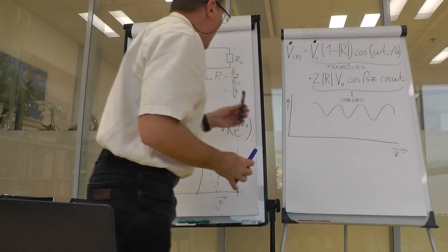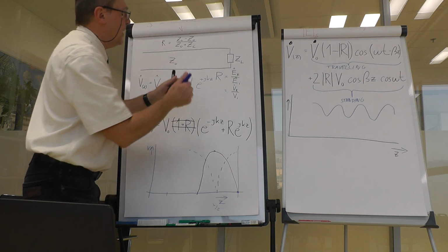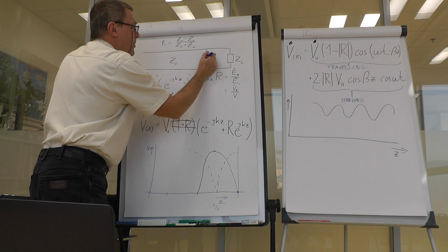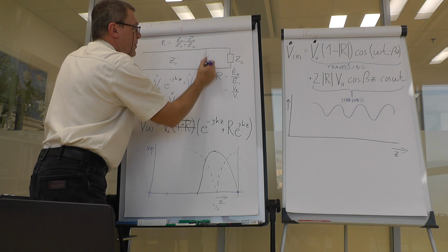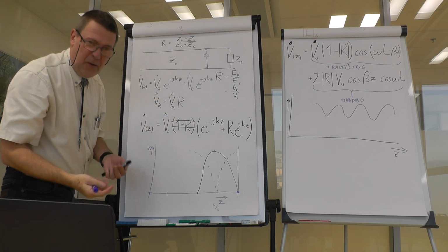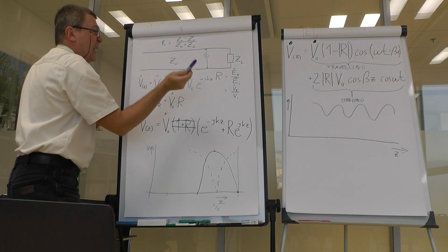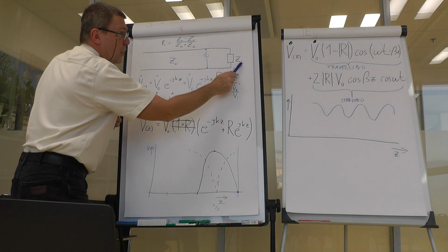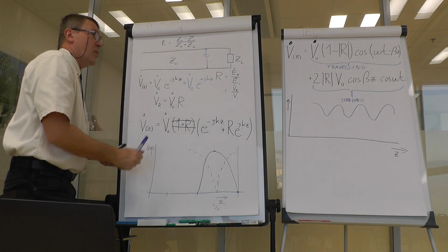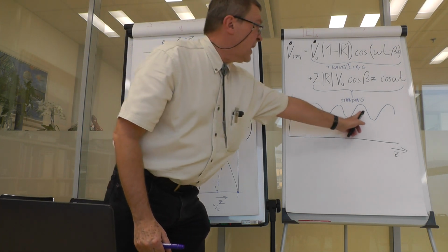If we would have, for example, a probe, a voltmeter, connected just on the line, or a voltmeter with a rectifier, and we would move it on the line in the case where Z0 would not be Z load, but Z load would not be infinite nor zero, we would get different readings of voltage on that voltmeter.